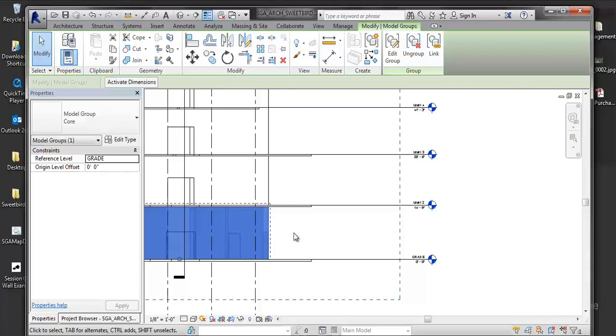That's because you still have a group of a group, so you need to make sure you ungroup it. Ungroup everything? No, just the ones you copied, because they're different. So think of the group like an AutoCAD block. Gotcha. So you ungroup it and then you regroup it and rename it, like core level 2 or something. Yep. Like that. Okay, got it. Cool.